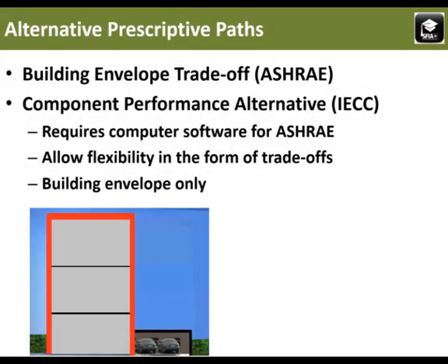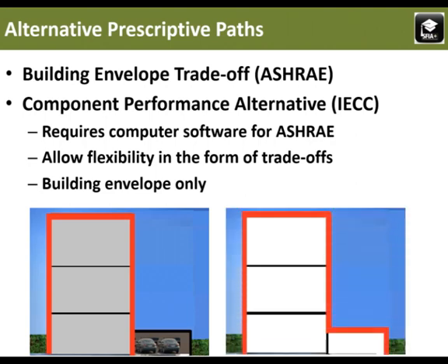We've mentioned the thermal envelope a few times now. It's a simple concept, as shown here in this sketch of a 3-story building with a covered parking area off to the right. The thermal envelope is the area that separates conditioned space or semi-conditioned space from unconditioned space. This is shown in the red. Note the garage area is not conditioned, but if it were, the thermal envelope would look like this.